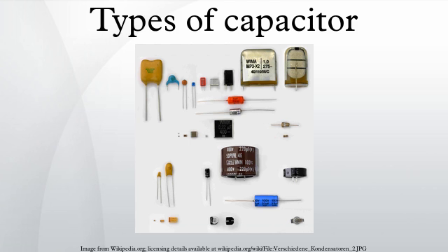Double-layer, lithium-ion and supercapacitors. Class X and Class Y capacitors. Many safety regulations mandate that Class X or Class Y capacitors must be used whenever a fail to short circuit could put humans in danger, to guarantee galvanic isolation even when a capacitor fails.